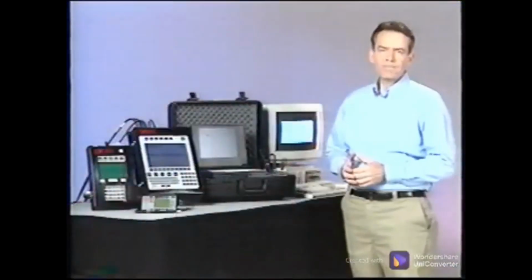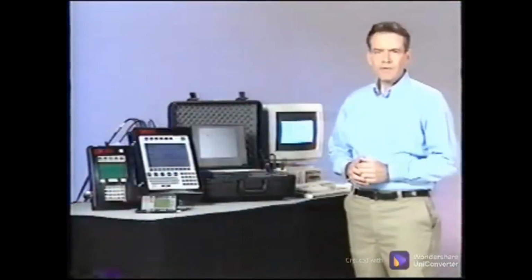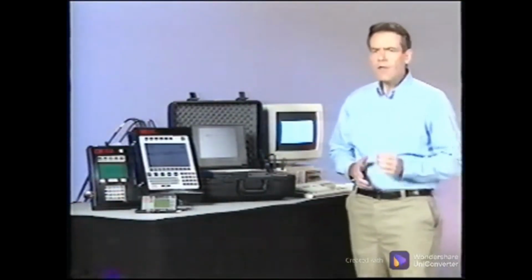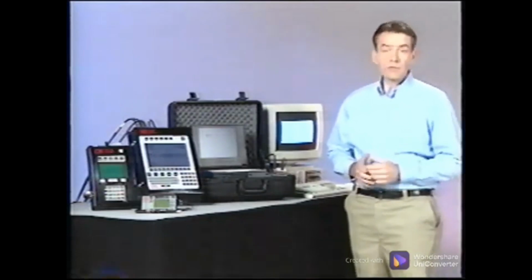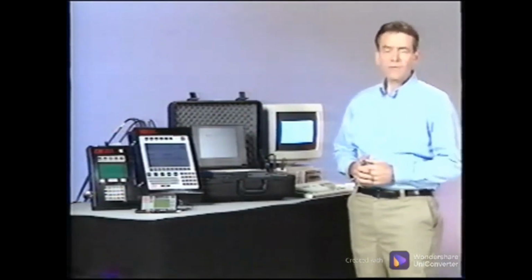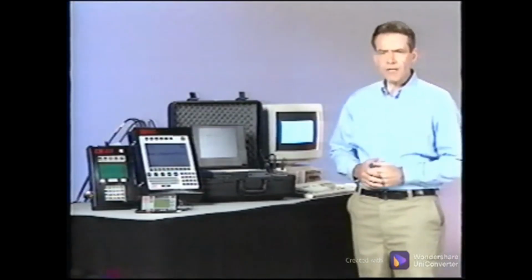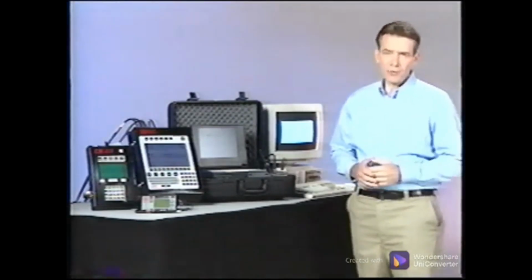In the previous section, we showed the importance of the waveform and the information it contains. We need to be aware, though, that the waveform may have limitations due to the limitations of the analyzer that can mask some critical problem. It is important to set up the measurement to obtain the information you need. We have pointed out that most of today's analyzers are digital and actually only store points that are then connected to show a representation of the actual waveform.